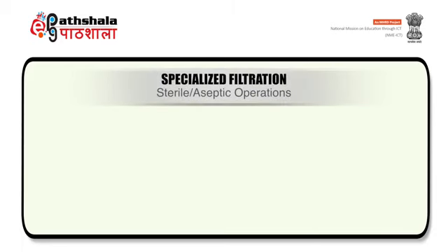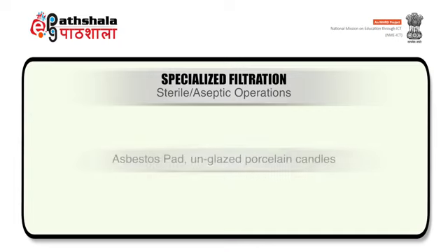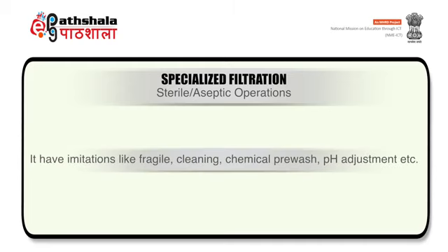Now we will discuss specialized filtration. One such filtration is sterile or aseptic filtration. The old and traditional way is by the use of asbestos pad and unglazed porcelain candles. It has limitations: it is fragile, cleaning is a problem, and chemical pre-wash and pH adjustment sometimes become troublesome.